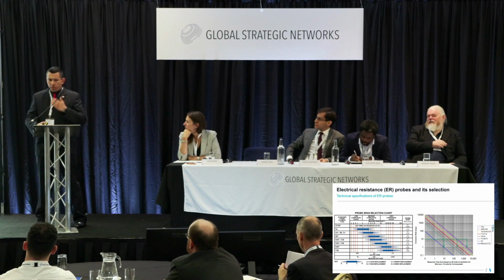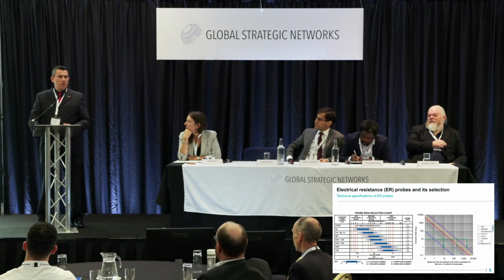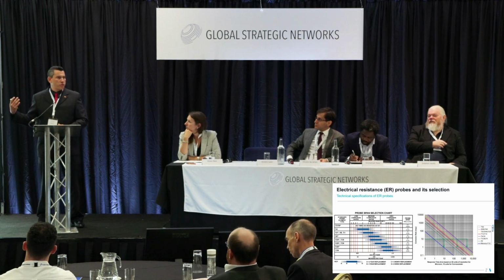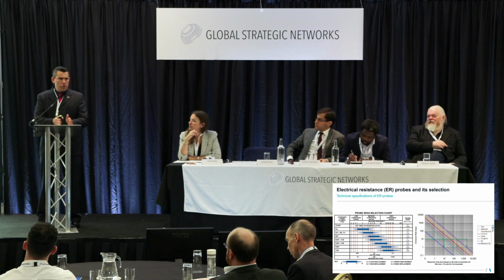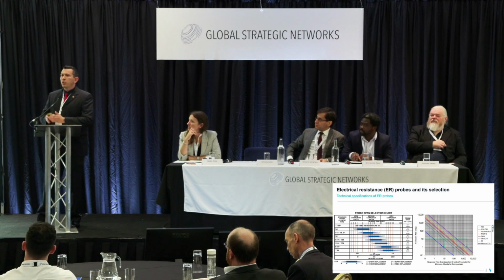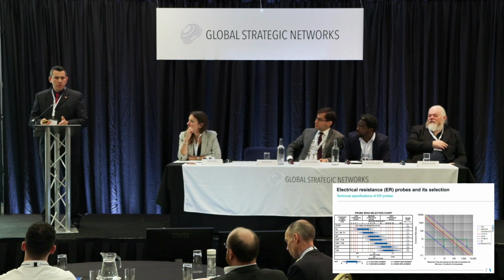And for some people, it might sound strange. Okay, like every 6 weeks, I need to change this. It's necessary. In refineries, for example, it's a no-brainer. They know that they have to replace these probes in a few locations, not all of them. Some other locations, you are happy to have a response time of 2 or 3 days, and you can replace them every 2 or 3 years.